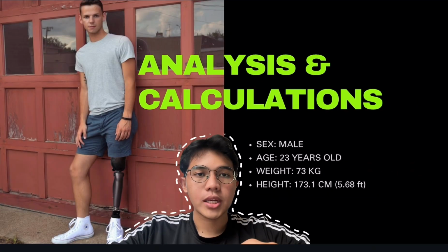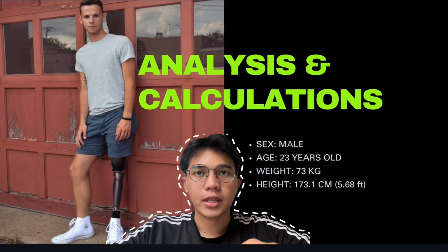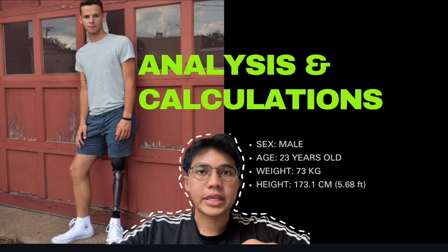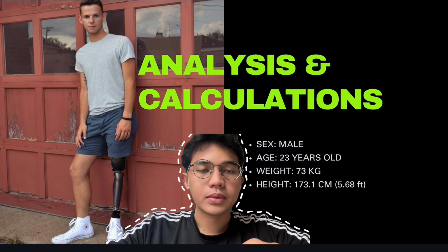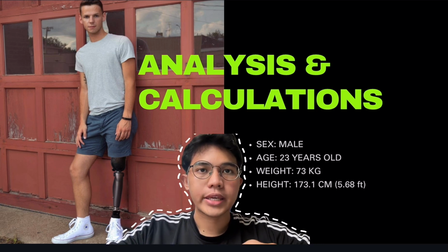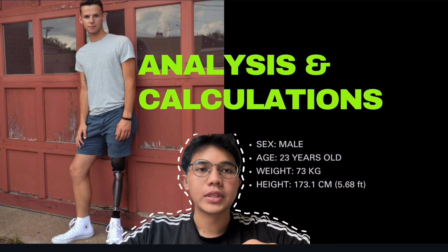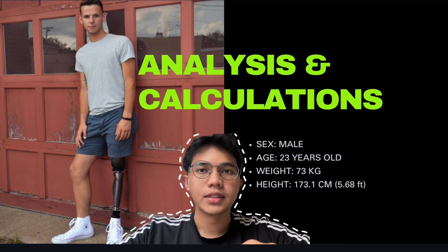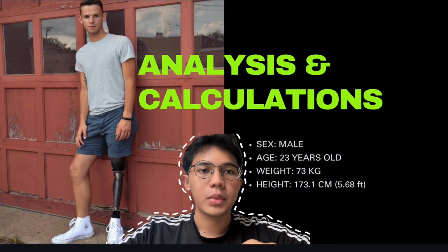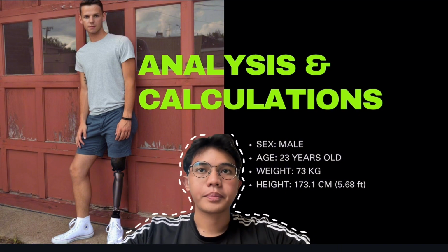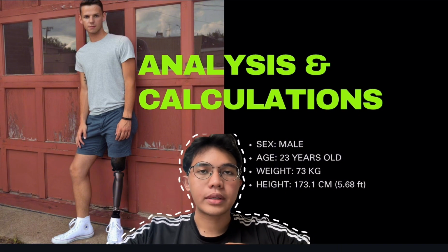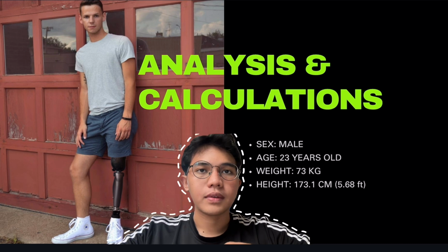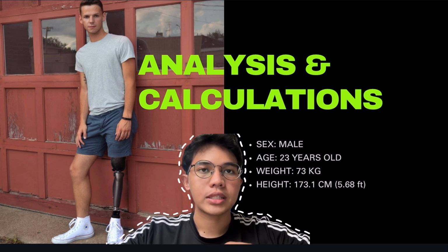Next, we are going to analyze and make some calculations for the prosthetic leg. Free body diagrams would be done of the leg in one phase, which is the mid stance in the gait analysis. Then we will assume parameters such as the mass of the legs and the mass of the device to calculate the forces and moments acting on the leg. Now, the subject that we took on is only one subject. Sex is male, age of 23 years old, weight is 73 kg and height of 173.1 centimeters.